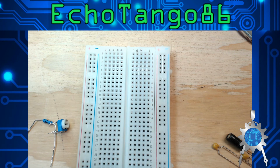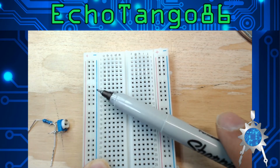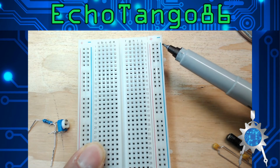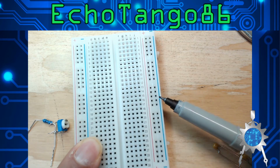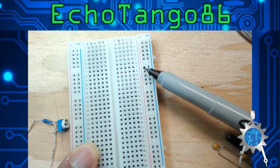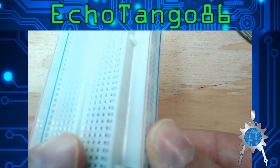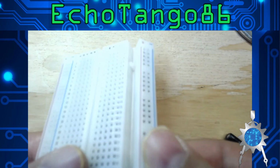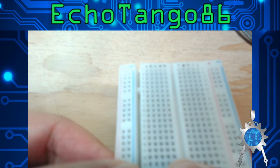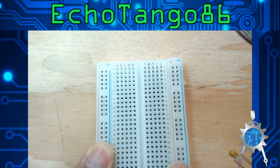But anyways, so this is the breadboard. What you're usually going to see is two ends that have red and blue written on them, a little plus and a minus. The way the breadboard works is that your negative, this is your ground, is all connected this direction, up and down. And that's the same for your positive, up and down. But it's literally not connected to the board. Has no connection. You see, I split that apart. And the other end, same thing. It's separate. So you don't have to worry about positive and negative touching and grounding out and shorting your board.